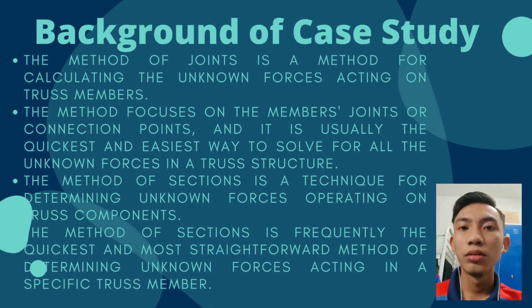We also have to guess whether it will be a tensile or compressive force. An incorrect guess, on the other hand, will simply result in a negative solution later on. A common strategy is to assume that all forces are tensile, and that any positive force will be a tensile force and any negative force will be a compressive force later in the solution. Each force in the diagram should be labeled, include any known magnitude and direction, and give each unknown a variable name.